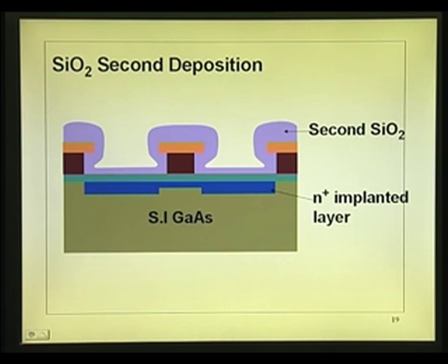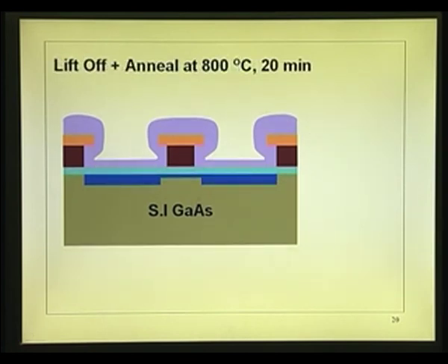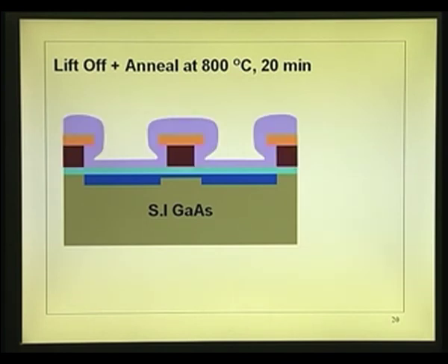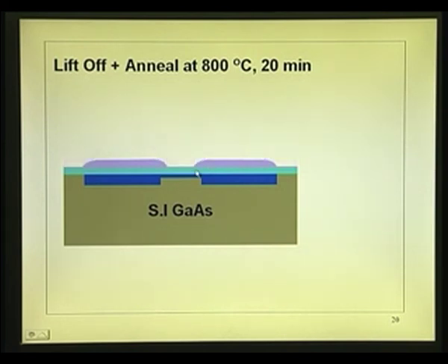Key thing is I just put it in a solution which dissolves the photoresist. Okay? This is the photoresist, this is SiO2. I put it in a solution which will dissolve that. What will happen? Whatever is above that will go, that is lift off. See, whatever was there over this region, which is dissolved now in acetone, whatever is above that, including that oxide, goes off. Now, you have got defined N plus region channel, and you have got an opening here which is smaller than that.